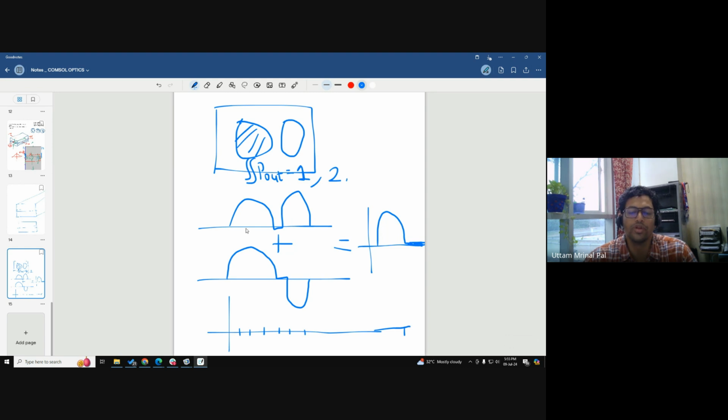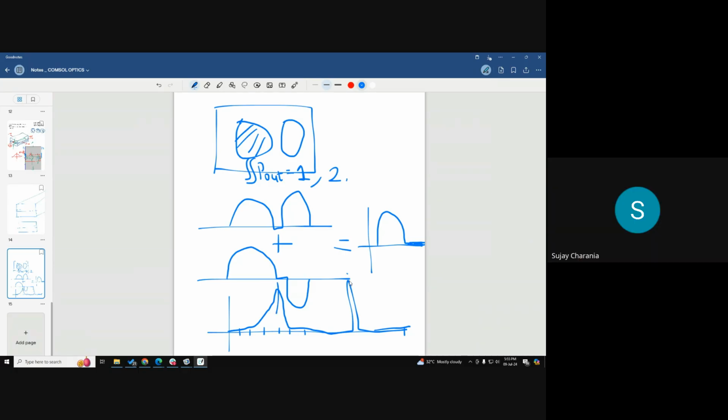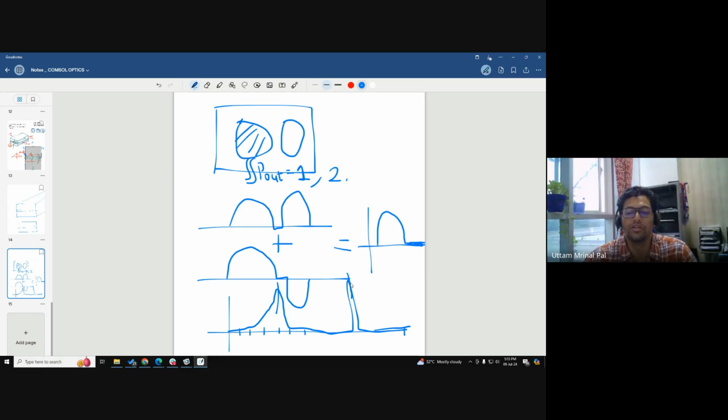So when the power flow is very high, it means that a lot of power is flowing through that particular mode for that particular refractive index, right? So you will see something like this. Sometimes peaks will happen, and those peaks are nothing but the fundamental mode and higher order modes. So you need to see when the power significantly increases at those particular effective refractive indices. You'll get the index, from 1 to 100, not the values, and then you have to correlate from the number over here to these values and then launch that, if you want to launch.